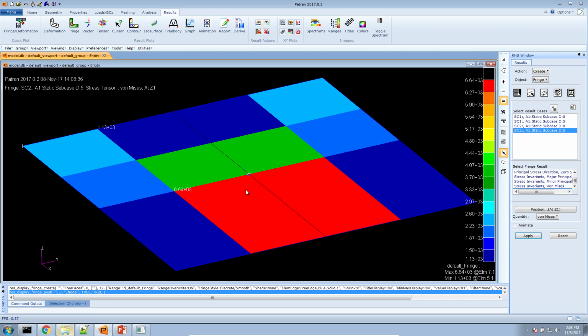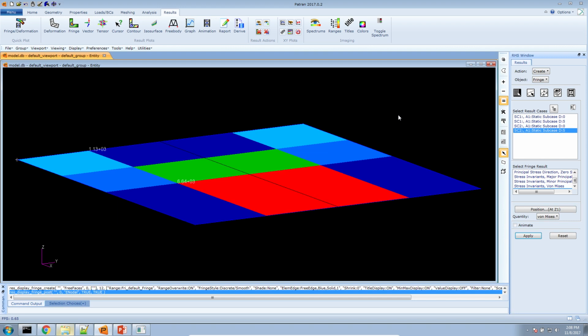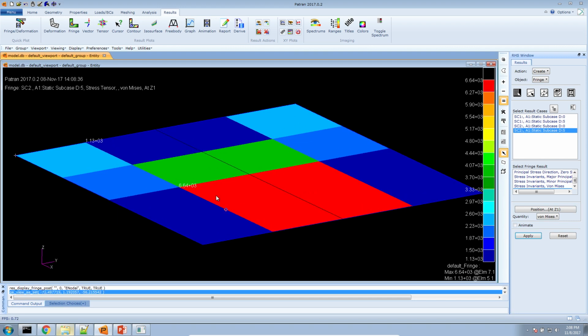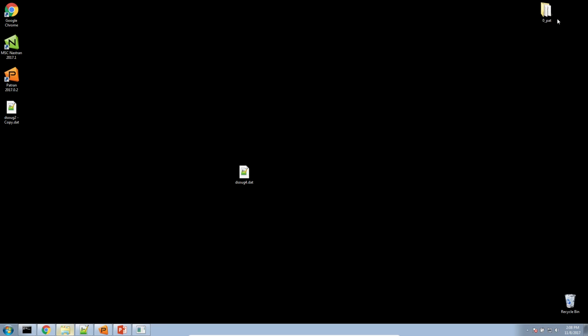I recommend doing this check just to make sure everything looks okay. On one occasion, I slipped up. I made my displacement constraint, or rather, I made my stress constraint 250,000 units of stress, and you should have seen the deformation on this plate. It was really high. So always make this final check just to confirm everything is reasonable. Let me go ahead and minimize all of this.